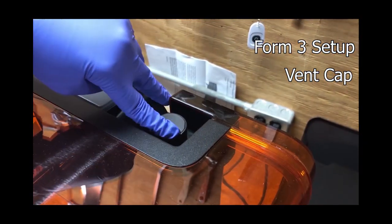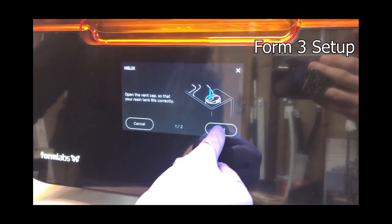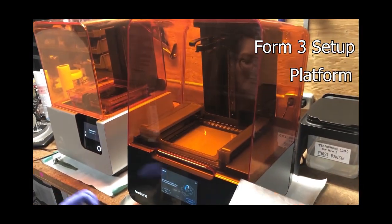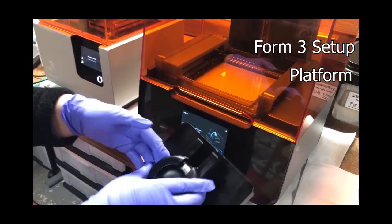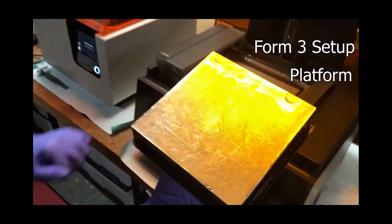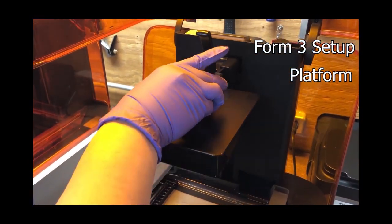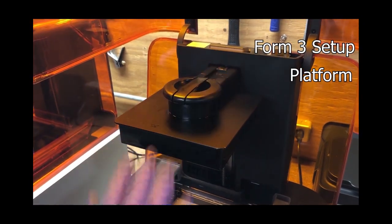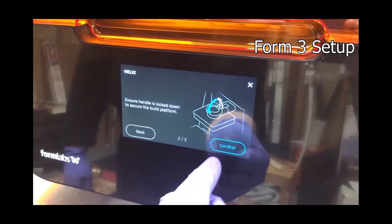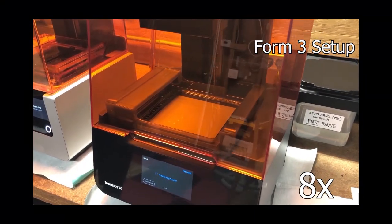It always reminds you to open up the vent on the cartridge, in case it needs to squeeze more resin out of the cartridge into the tank. Now I'm going to put the build platform in there. I had it out, but it should always be in there already. Make sure there are no parts stuck in there, and slide it back in. We only use clear resin, but if you are using the same build platform with different resins, you do have to clean it with IPA.